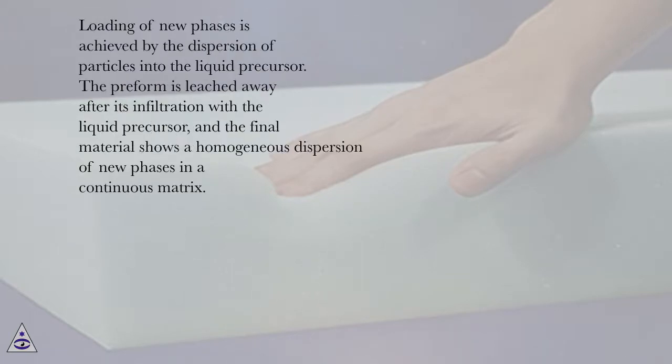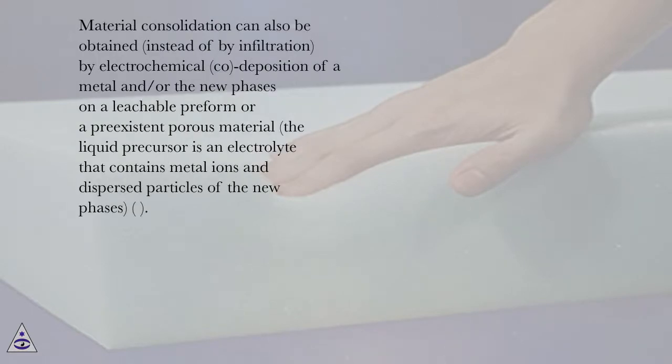Loading of new phases is achieved by the dispersion of particles into the liquid precursor. The preform is leached away after its infiltration with the liquid precursor, and the final material shows a homogeneous dispersion of new phases in a continuous matrix. Material consolidation can also be obtained, instead of by infiltration, by electrochemical deposition of a metal and/or the new phases on a leachable preform or a pre-existent porous material. The liquid precursor is an electrolyte that contains metal ions and dispersed particles of the new phases.